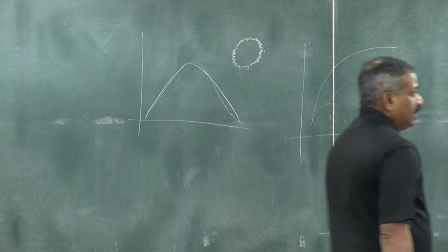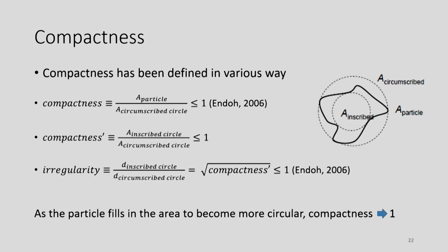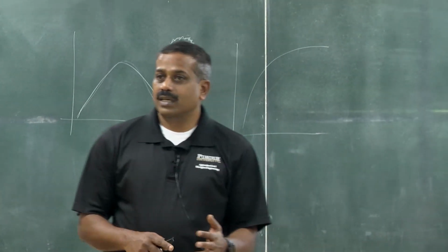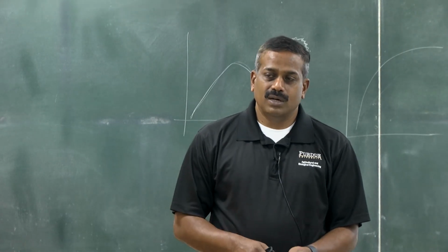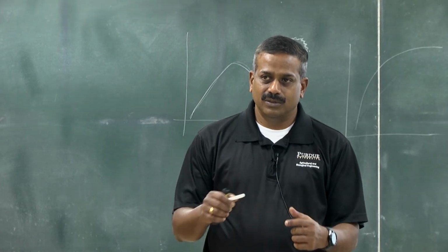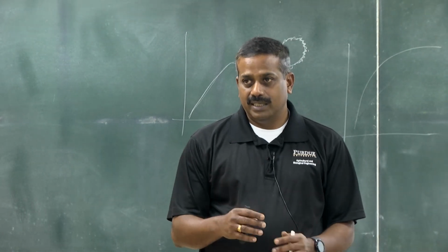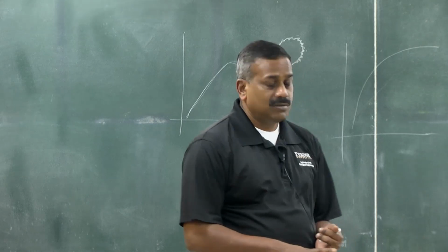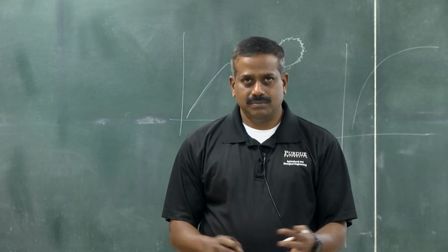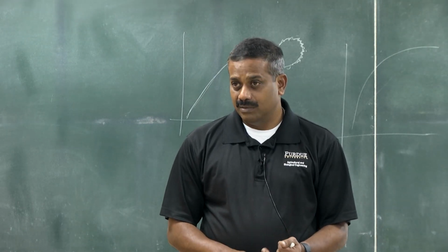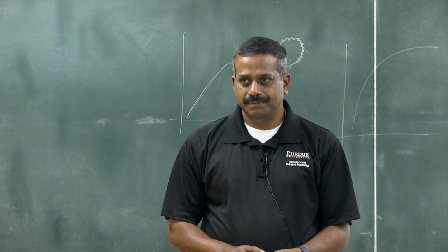The same thing with compactness. If it's very compact, then you may not be able to fit lots of particles within the pore spaces. Then you rely more on cohesive adhesive bonding rather than fitting the particles within the pore space. So circularity and compactness will come into play mostly when you deal with agglomeration, powder to powder mixing, adding some ingredients, etc. Is that clear?